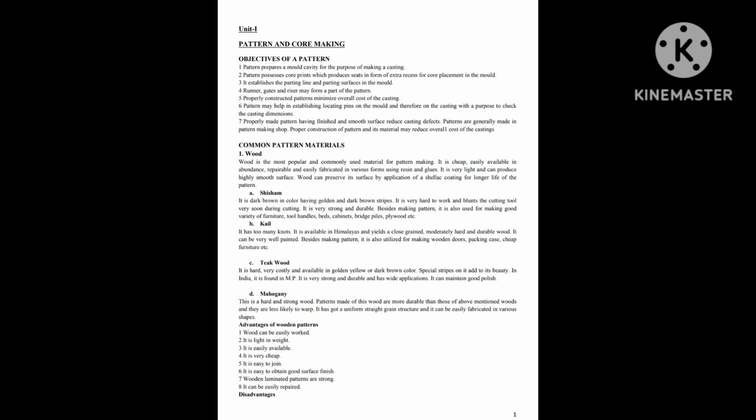4. Runner, gates and riser may form a part of the pattern. 5. Properly constructed patterns minimize the overall cost of the casting. 6. Pattern may help in establishing locating pins on the mold and therefore on the casting, with a purpose to check the casting dimensions.